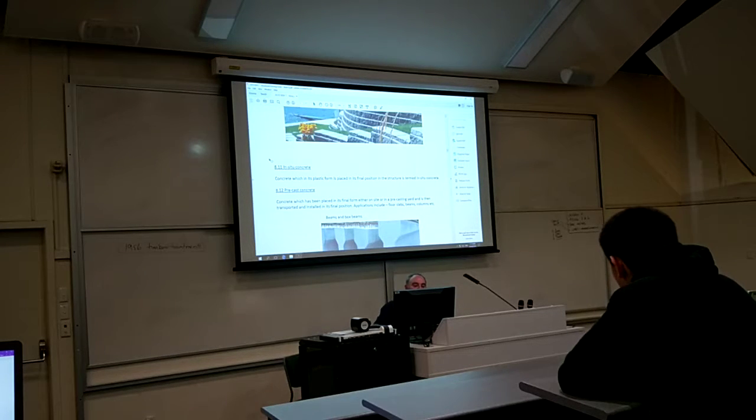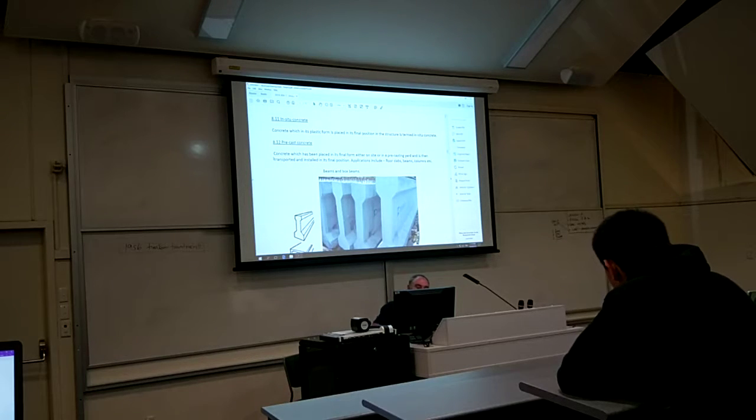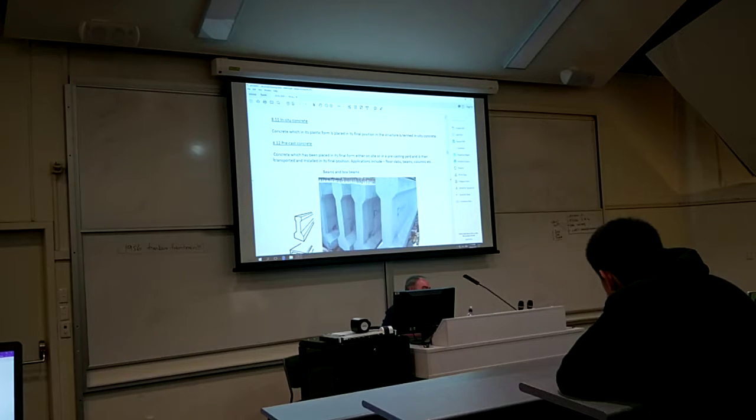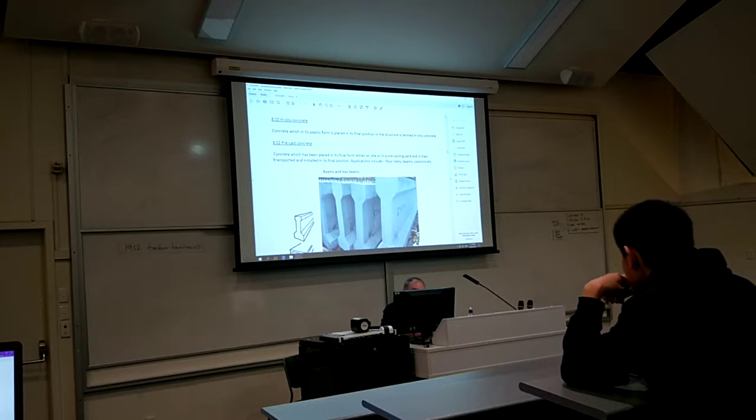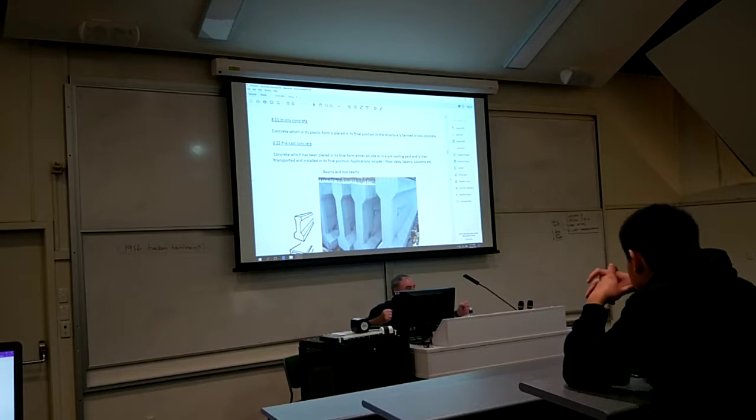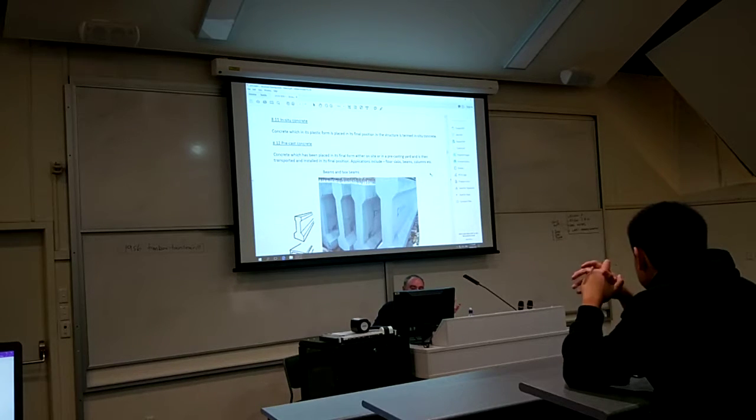Precast concrete. A good example of precast concrete like this is with beams and box beams for bridges. I had the privilege of seeing beams being put in place on a motorway job. They do it at midnight, of course, because that's when there's least traffic. And what these beams are is pre-tension. So what they tend to do is they tension the reinforcing, they pour the concrete, and then they let the tension off. So they're what we call precast beams, and they're extremely strong, and they're specifically for the likes of floor slabs, beams, and columns.